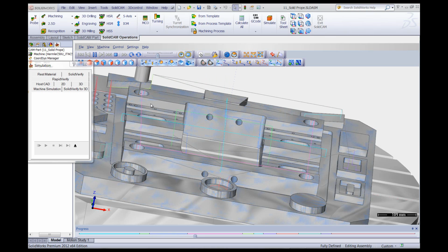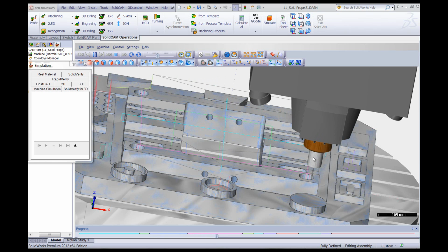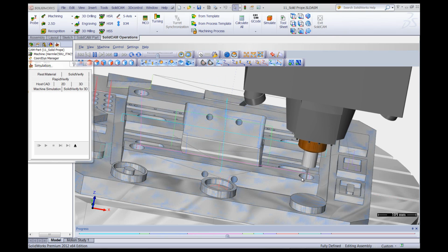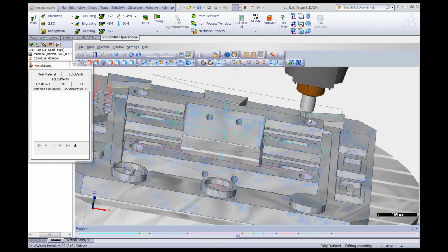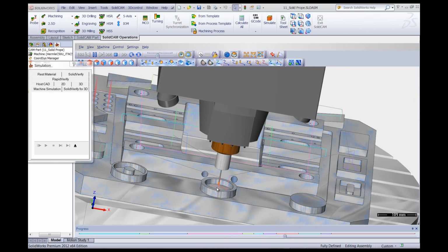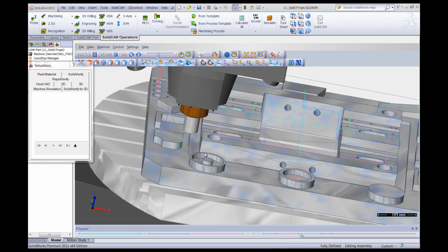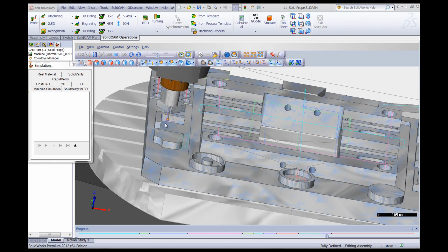and now into the holes themselves, doing the first hole, the second one, touching off on all 4 points inside the holes over there, the third one over here, and then the last one on this area over here. Now it's going to go over to this surface, measuring the angle in the Y-axis, and now this one in the Z-axis as well. Moving on to this pocket over here, and then to this circular pocket over here. Now we'll move over to this fillet as it measures this fillet over here, and then this corner as shown over here. And finally, moving into this area over here,